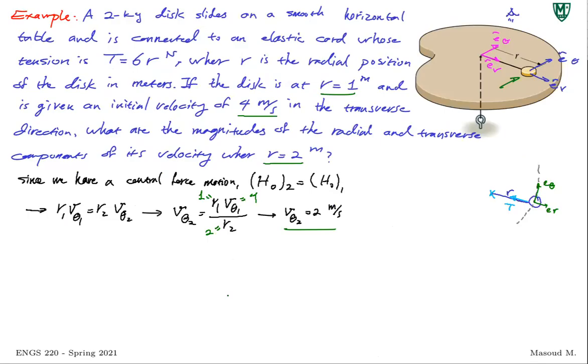You have to be able to look at the problem statement, see what you're given, and think about what kind of method you can use to get to what you want. You can't use linear impulse and momentum because there is no information about time here. Since you're talking about the relationship between force and position, think about energy methods.